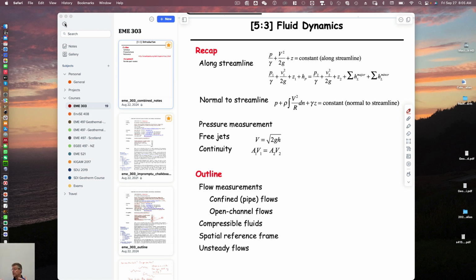Of course, the question is different. You end up in the same place, but you don't get told you have to calculate this, and then calculate this, and then calculate this. It just said calculate the average density for a mixture of X alcohol and 1 minus X water, calculate the average surface tension, calculate the height rise. You've got the height rise, use this figure. If you change the mix 70-30 to 30-70, what do you get?